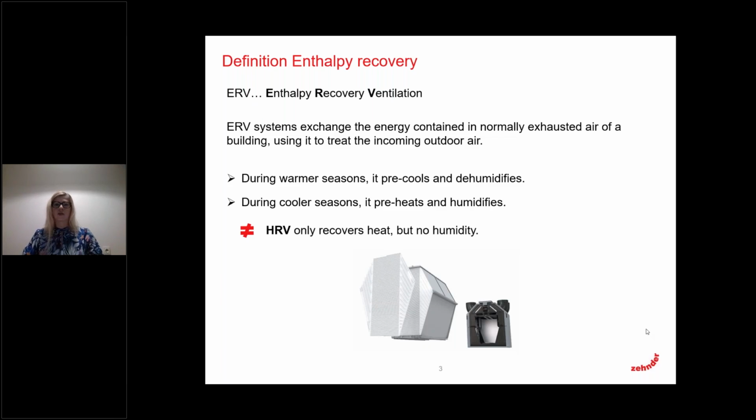During the colder seasons, which is usually brought as an example when we are talking about heat recovery ventilation, we have water that is heated and we are using energy for that, and therefore there is no reasonable way that we would just let that energy go out of the window, because we also want to have fresh air inside of our house. Then we are using heat recovery to use that energy, which we have already used, to heat the house. With this, we are heating up the cold outdoor air. So the heat exchanger is working as a preheater.